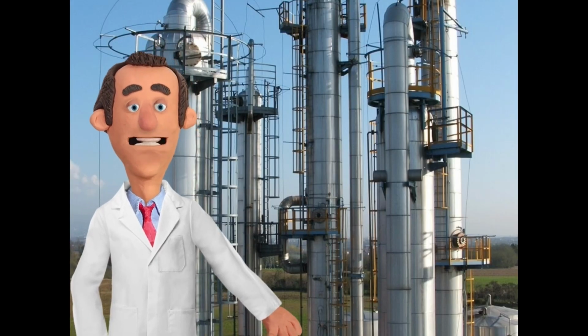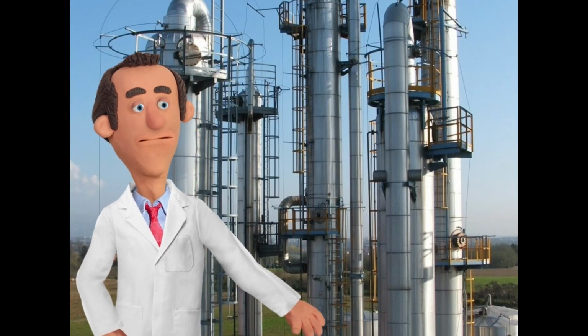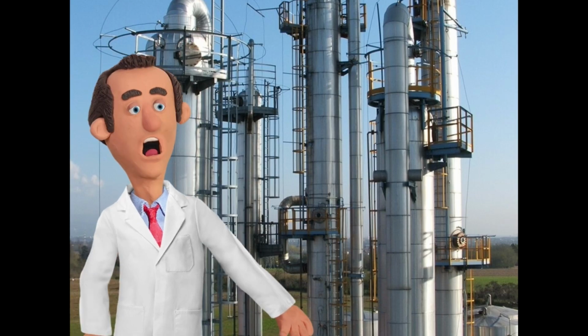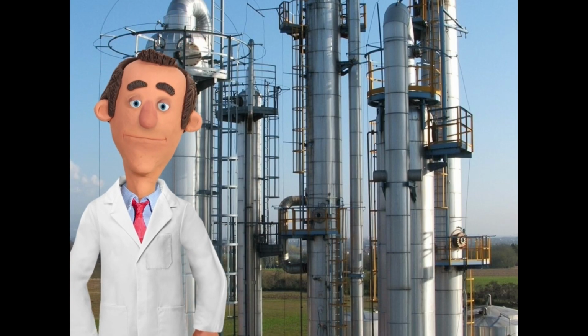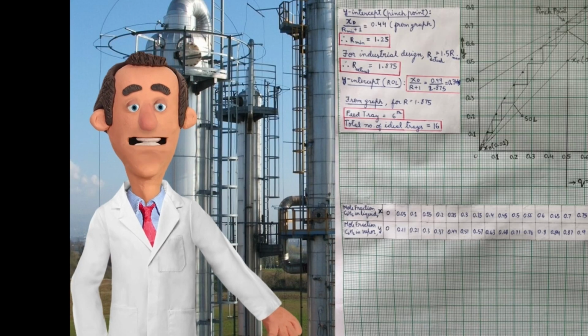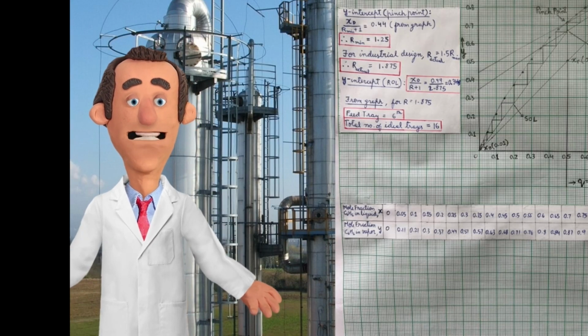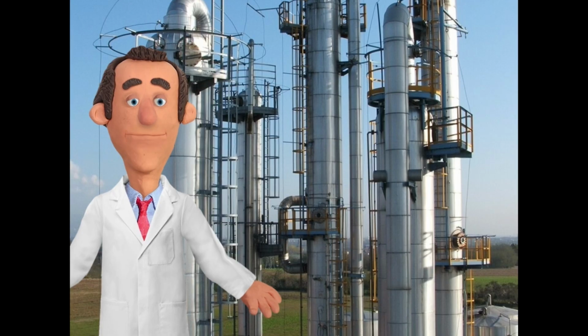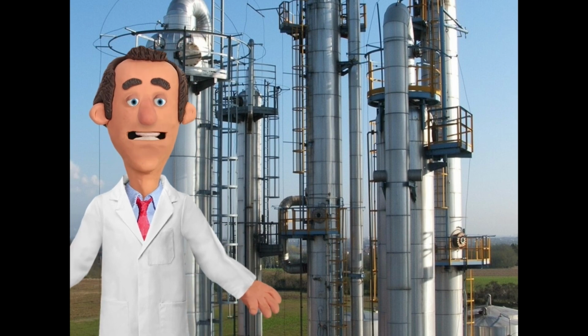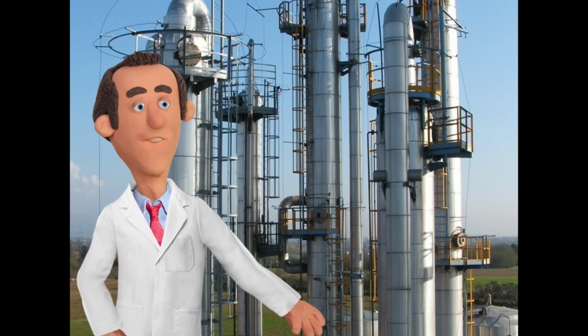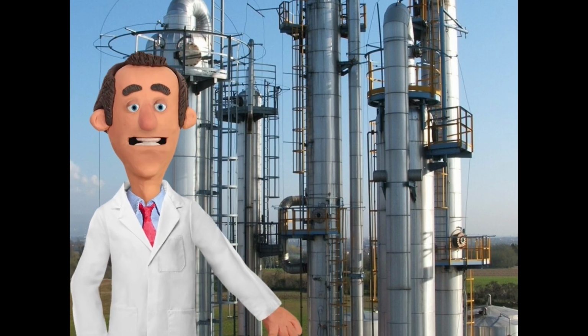Chapter 1. Designing the distillation column using McCabe-Thiele Method. The goal here is to develop an initial column design before simulation. So I used McCabe-Thiele graphical method for separation of a benzene-toluene mixture, where benzene is the more volatile component. The column is designed for the purity demand from the customer: 0.99 distillate benzene mole fraction while maintaining benzene mole fraction of 0.01 in bottoms product.